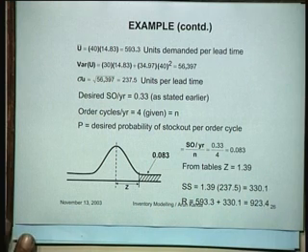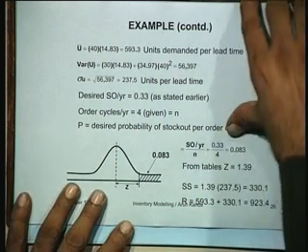This is how you can compute the reorder point, that is, when you should place the order. That is the size of the second bin in a 2-bin policy. That's what we are talking about.